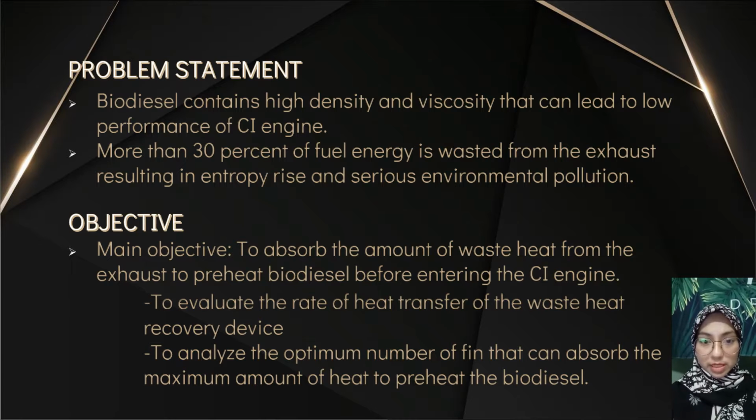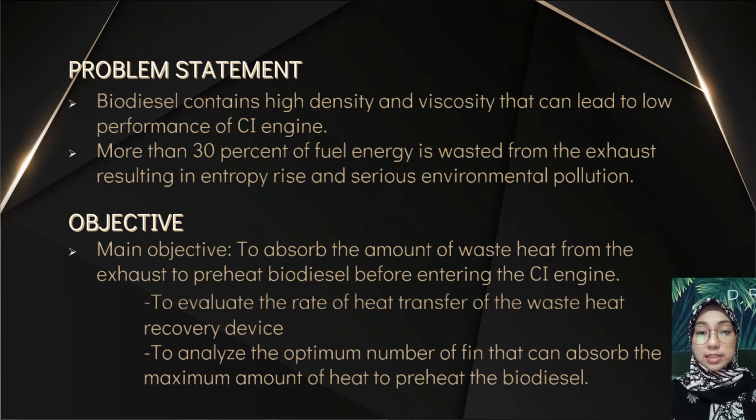For the problem statement, biodiesel contains high density and viscosity that lead to fuel flow and ignition problems and high emission in unmodified CI engine due to the difficulty in atomization and vaporization.